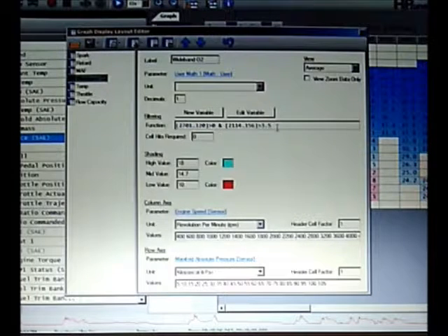The computer will just retard the timing on its own, because when you take your foot off the gas pedal, it's implied that you want the car to slow itself down, right? So reducing the timing will do that. The car usually does that for you, drops it down to 20 degrees or something like that. And it also usually leans out the fuel mixture, because again, you don't need gas, you don't need to waste gas going into your cylinder when you don't want the car to accelerate.